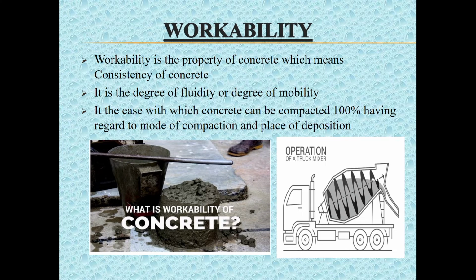Workability, in other words, is the consistency with which concrete can flow with less compaction and without any loss of its properties. It is the degree of mobility or fluidity of concrete with which it can flow when placed from the pan or the mixer.